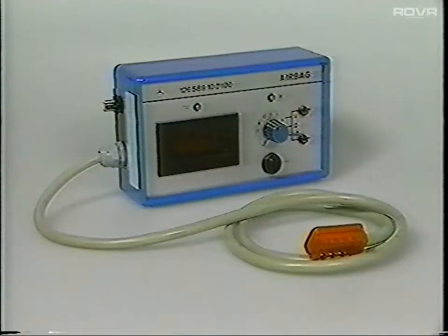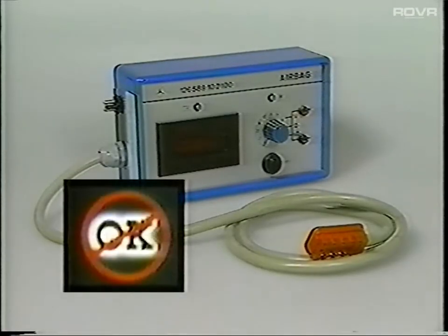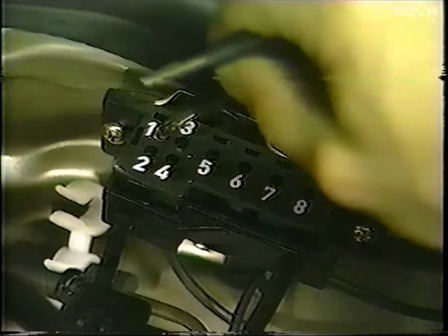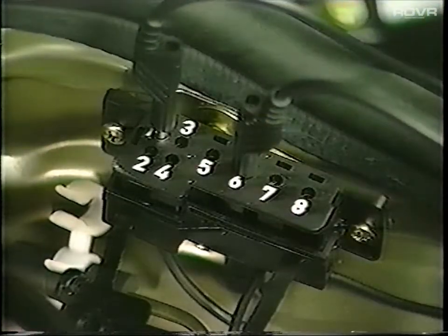In fact, because of changes to the components and operating characteristics of the system, the test adapter previously used for diagnosing SRS cannot be used for testing 1988 model year vehicles. To obtain diagnostic information using the SRS warning lamp, Terminal 1 and 6 of the test connection are connected to a jumper cable.